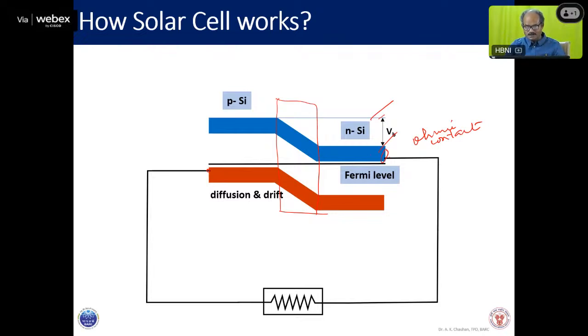What are those two kinds? One is radiative recombination, and the other is non-radiative recombination. If it absorbs this much energy and falls from this to this, and this energy falls in the visible range, a photon is emitted, and that is the radiative recombination. Or if it doesn't come directly here but comes through different states, emitting small energies, that energy doesn't give a photon. It actually goes in the form of heat, and that is the non-radiative recombination.